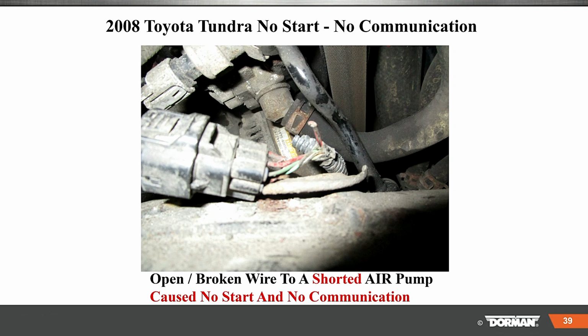So here, with a look, we see this no start, no communication, an open broken wire to a shorted air pump. So the air pump was shorted. The hose, water usually gets in there. We found a lot of these.